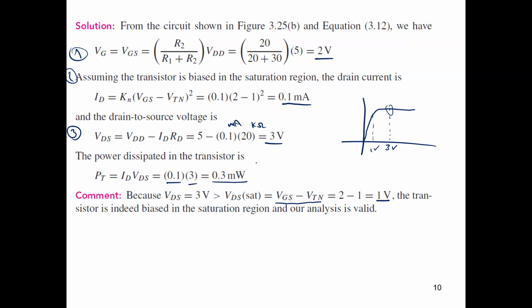However, the power dissipation across a power electronics or electronic element, especially in power electronics, is more complicated. For instance, in power loss, we have 3 terms of power loss. It's not just one term like that. We have what's called conduction loss, switching loss, and gating loss.